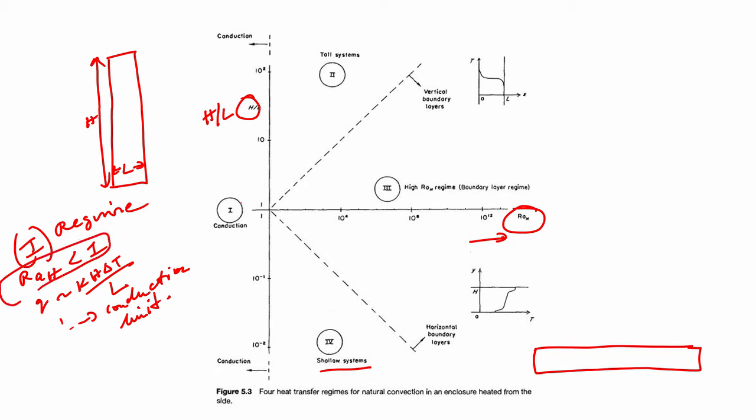That is why all these sectors converge in this region, where we are considering the solution, because it is in the Rayleigh number less than 1 range. So, this entire band is wholly conduction, if you can see it properly. So, that is regime 1. Regime 1 is done and dusted. Let us look at regime 2 now.